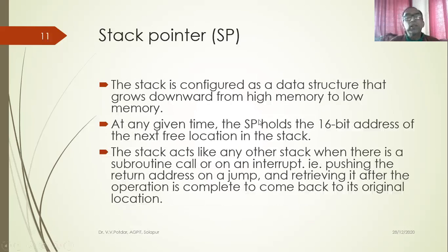For stack pointers, the stack is configured as a data structure that grows downward from high memory to low memory. At any given time, the stack pointer or SP holds the 16-bit address of the next free location in the stack. The stack acts like any other stack, which is nothing but a pileup of information, right? And when there is a subroutine call or an interrupt, it pushes the return address on a jump and retrieves it after the operation is complete to come back to its original location. This is a function of your stack pointer.